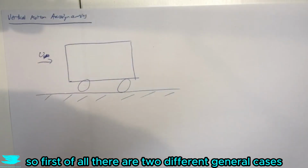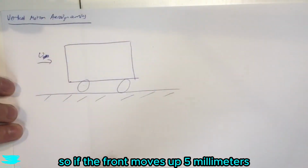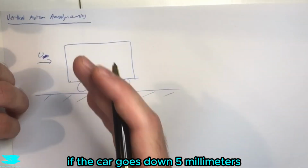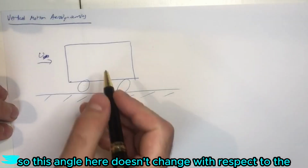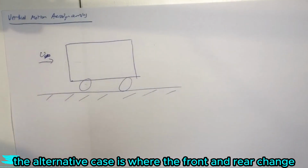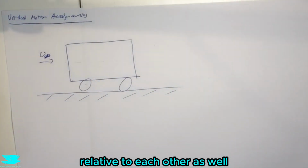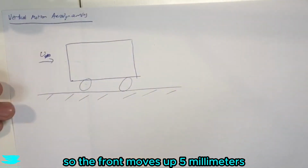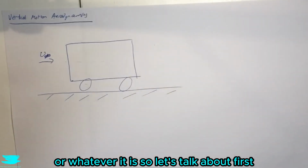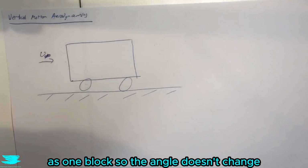So first of all, there are two different general cases. The first one is where the entire car moves up and down together. So if the front moves up 5 millimeters, the rear moves up 5 millimeters too. If the car goes down 5 millimeters, again, the rear 5 millimeters as well. So this angle here doesn't change with respect to the incoming flow. The alternative case is where the front and rear change relative to each other as well. So this angle actually does change. So if the front moves up 5 millimeters, the back might move up maybe 1 or 2 millimeters or whatever it is.